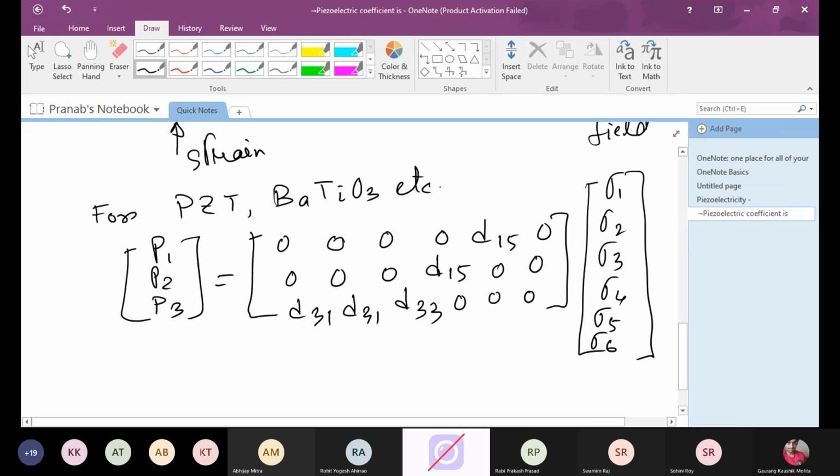So therefore, if we give stress in arbitrary directions, we may not get sufficient electric displacement of charge. So we have to identify the corresponding stress directions along which the charges will be available, and on what surface the electrodes need to be deposited. Then we will be able to collect the charge. I think we will discuss those a little bit further.